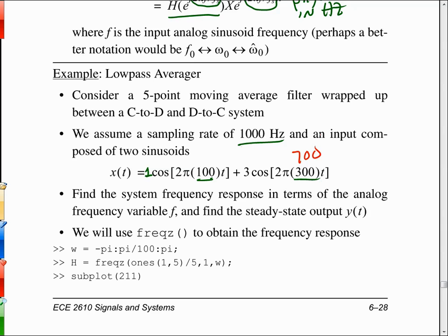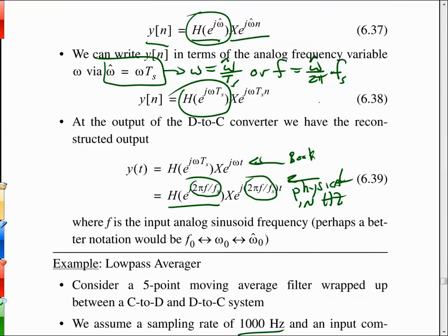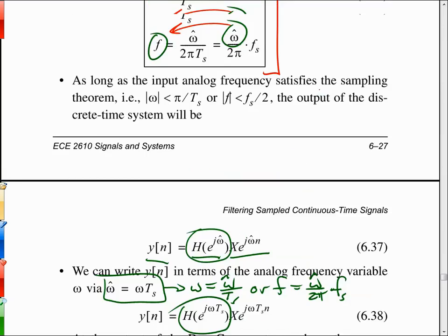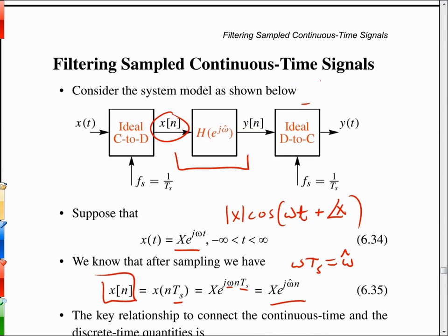So the way the math would work is, as soon as the signal gets sampled and violates sampling theory in this block diagram, which is way up over here, as far as the rest of the system processing goes, if the 700 aliases to 300 effectively, it's going to go through that filter as if it were originally at 300, because the digital filter knows nothing else except the principal alias value.